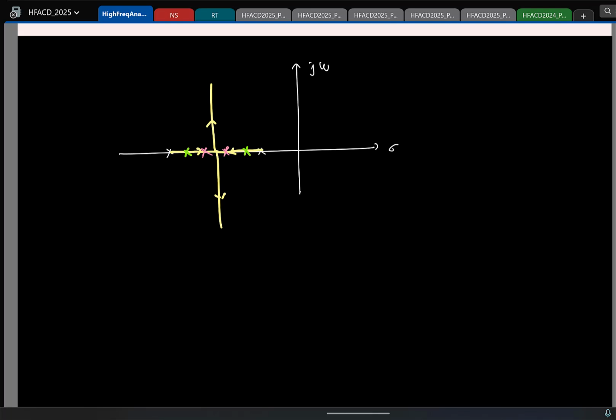No. See, this is definitely stable. Second order system, right? Second order system is definitely stable. No confusion. Now, I want to understand where you want the closed loop poles to be. We are on the same page that the closed loop poles must be on the real axis. But on the real axis, I can choose multiple possibilities. I can choose them to lie somewhere here so that they are far apart, or I can keep them close enough. Which is better? Why?